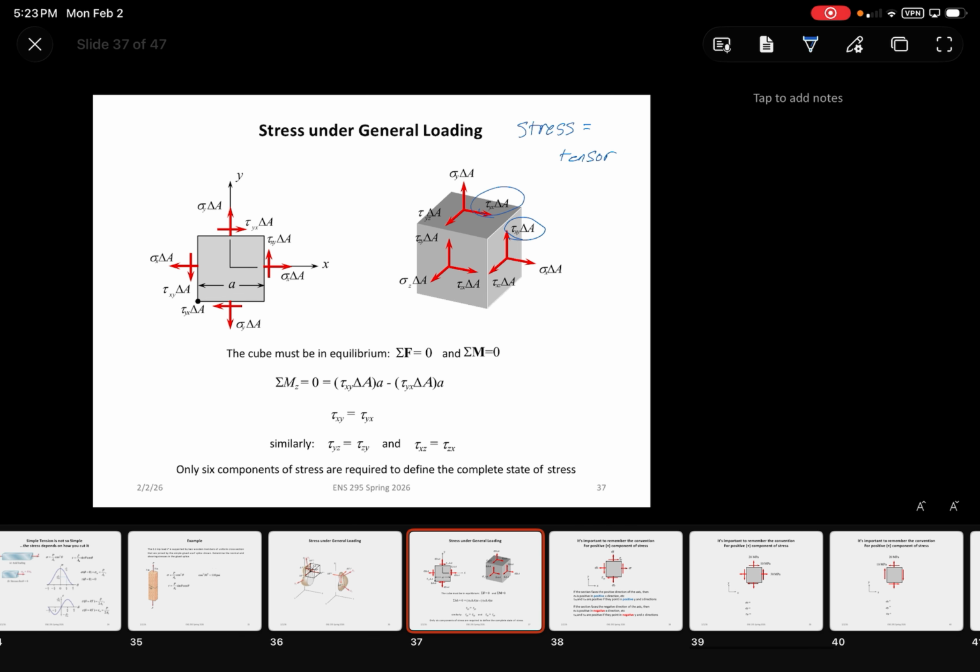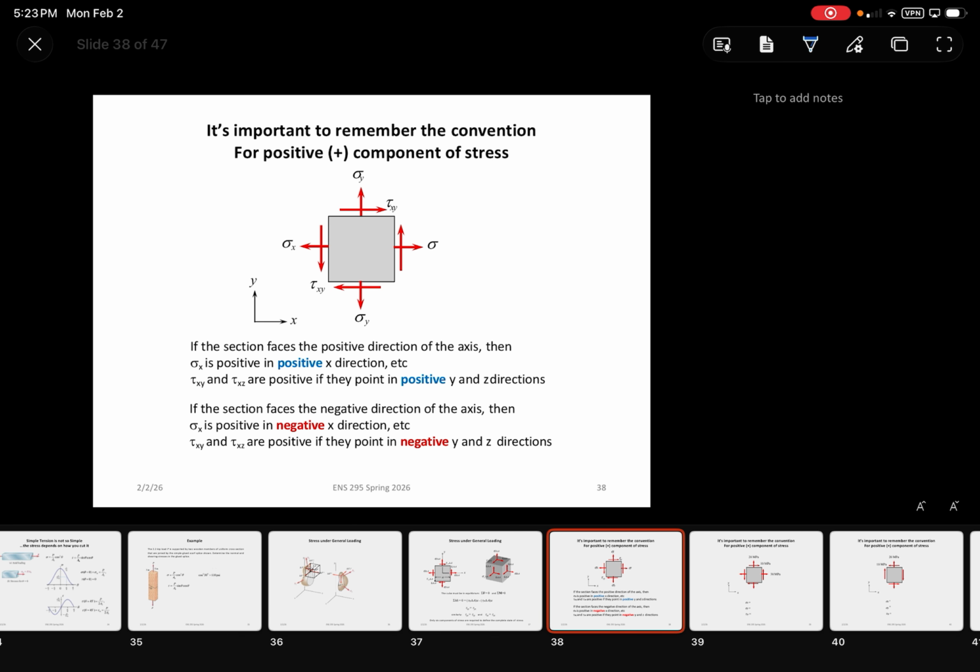Now, stress is going to obviously have its own sign components. For example, when you were dealing with truss members, you had compression and tension members, and you basically looked at the direction that the forces were going with respect to either the joints or the members themselves. In a similar way, we have a general orientation for stresses, where anything that acts in tension would be considered positive, and anything that acts in compression would be considered negative.